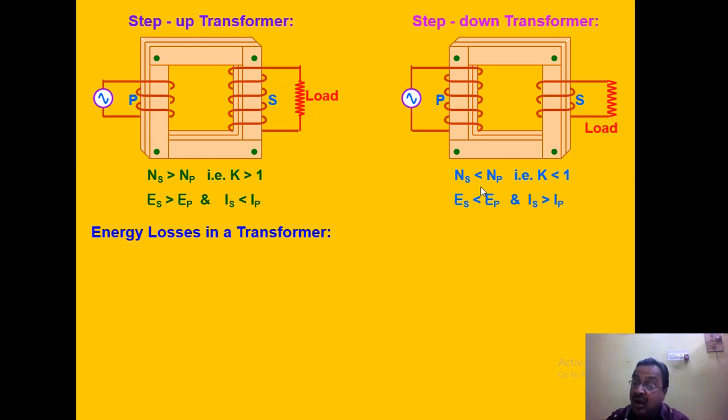And generally, although under ideal conditions we may say that efficiency is 100%, while performing there are losses of energy in different forms. In the case of a step up transformer, even if voltage is increased, current is decreased across the secondary. So a gain in voltage across the secondary will result in a consequent loss in electric current through it, and vice versa.